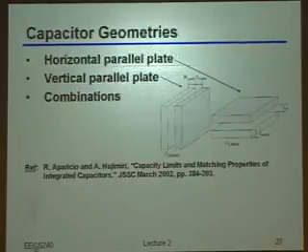So the way you would actually do that, and by the way, these capacitors that just use the existing metals are often what's called MOM capacitors. Don't ask me why MOM, that stands for metal oxide metal. So don't ask me why that's really all that different than a metal insulator metal, because the insulator is usually an oxide too, but this is just the terminology. Okay, so if somebody says MIM, that's like, costly, expensive, bad. Somebody says MOM, that's like, okay, it's standard, exists anyways, don't worry about it.